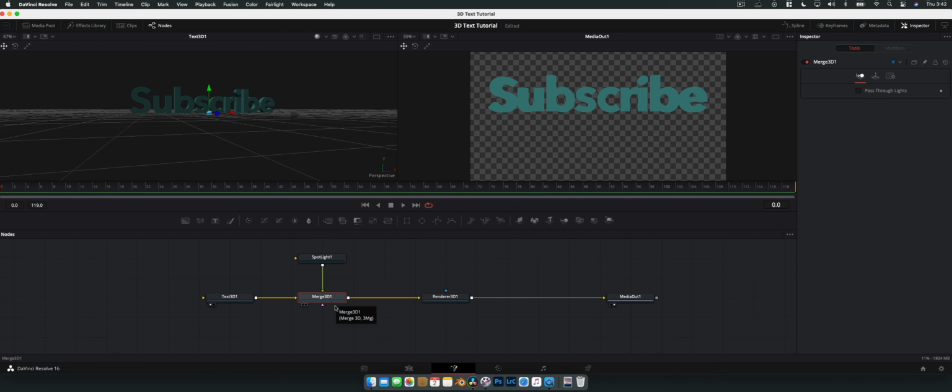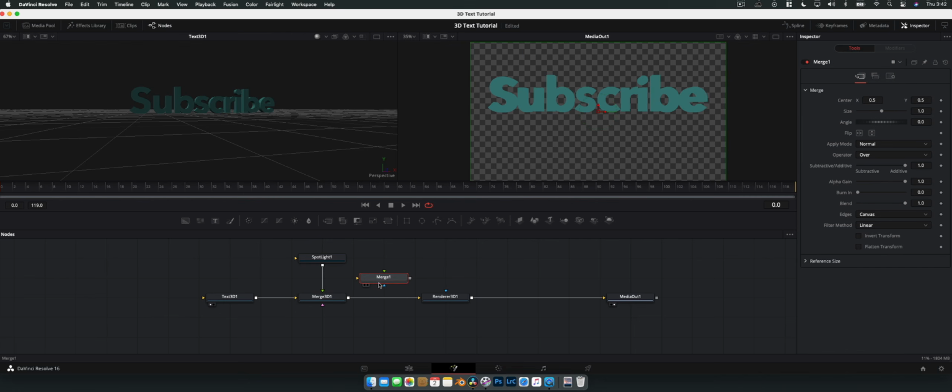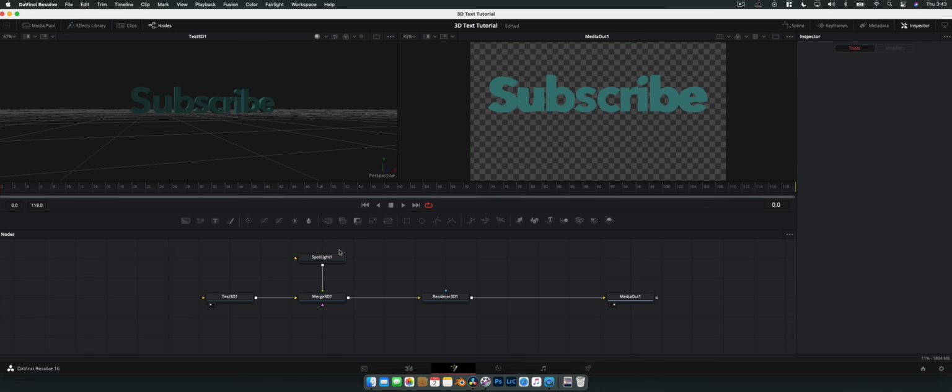Hopefully, if you guys have been using Fusion for a bit and following my tutorials, some of this is going to start to look a bit familiar, because over here we have a normal Merge node, Merge 1, and we've got Merge 3D 1. They operate in the exact same sort of way. They connect different elements of your composition together, allowing you to then output them to a single node. However, with a 2D Merge node, as you can see here, we have our background, foreground, mask, and then our output. With a 3D node, there is no limit to how many inputs you can have.